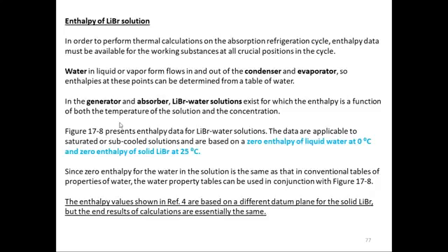Now it is for this solution which is in the absorber and the generator. How to find out the enthalpies there? So one part we covered, how to find out the concentration of lithium bromide in those containers using the chart. For the enthalpy, we are going to use another diagram. In the generator and absorber, lithium bromide water solution exists, for which the enthalpy is a function of both the temperature of the solution and concentration. Figure 17-8 presents enthalpy data for lithium bromide water solution.